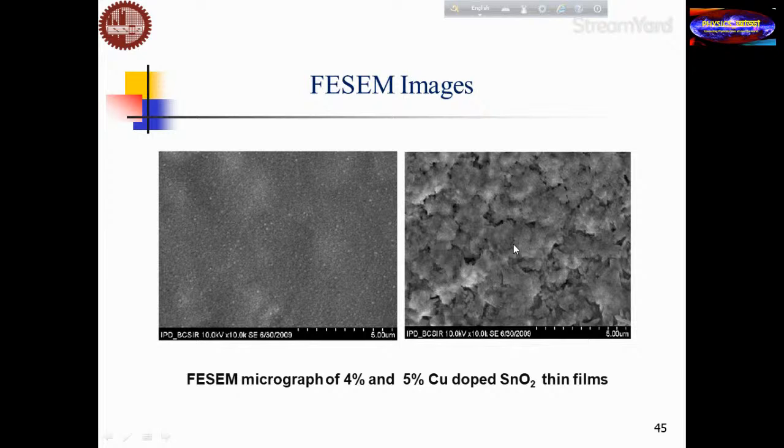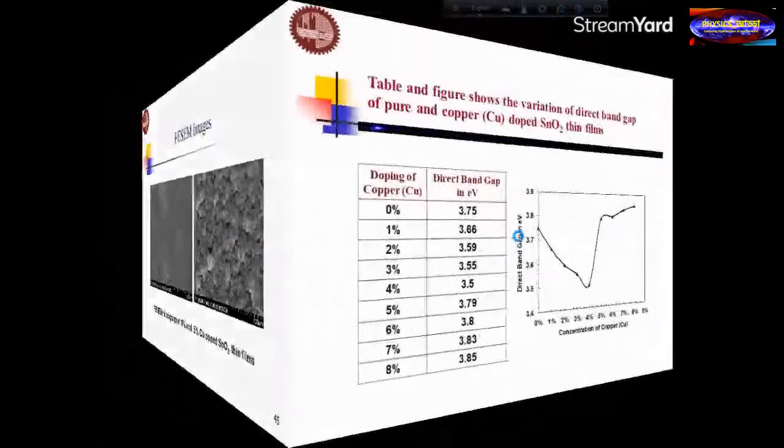But the speciality is, if we want to fabricate a sensor material, we need porous structures, because porous structures can absorb the gas molecules. So the advantage of these films is to produce porous structures as much as possible, as well as small crystallite size. These are all the criteria we need for application in sensing purpose. So that is the image we got on the tin oxides.